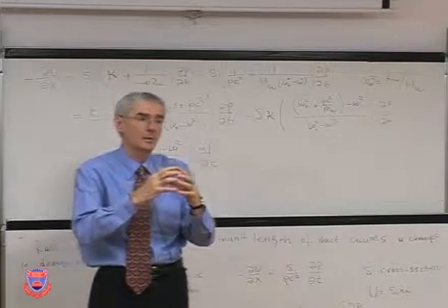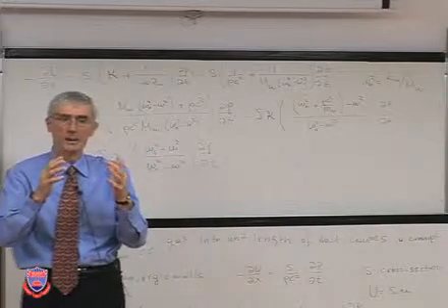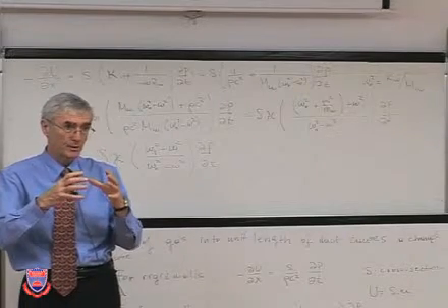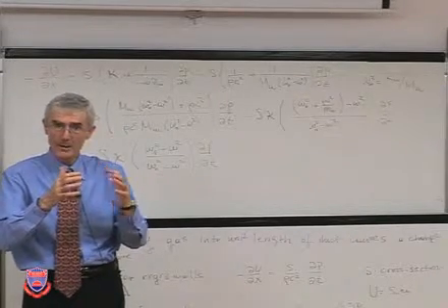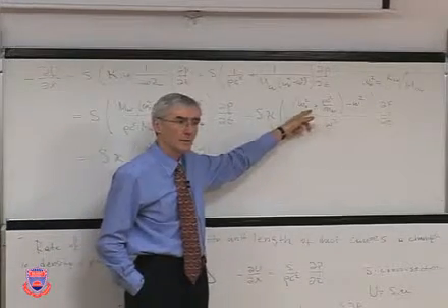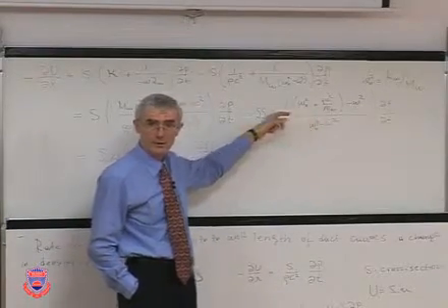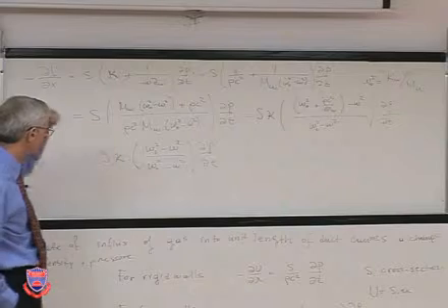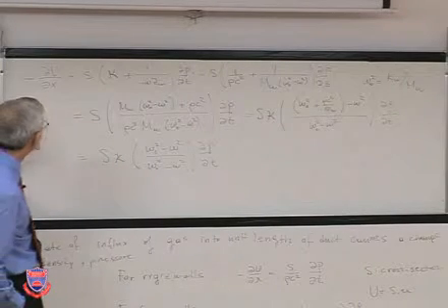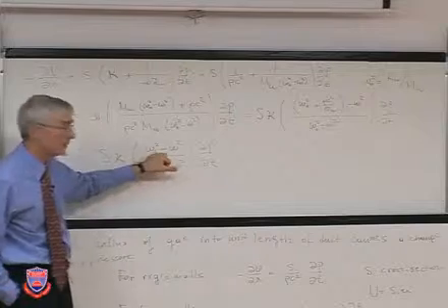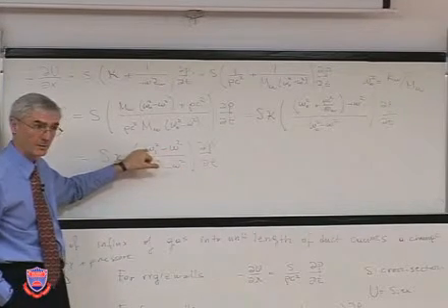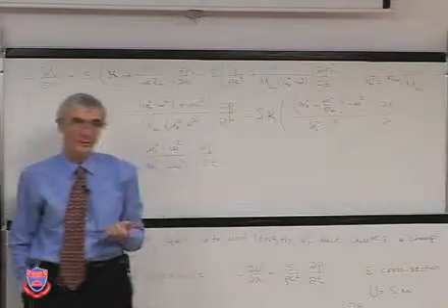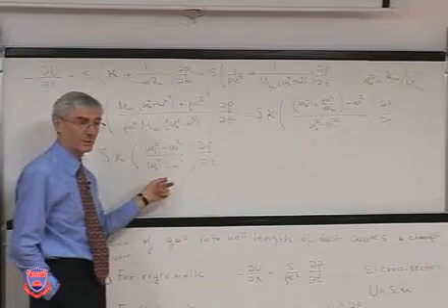Because it's like a balloon, okay? The membrane is not very stiff when you don't have air in it. But the higher the pressure in it is, the stiffness is somewhat different. So this is just a little bit addition to it that changes its stiffness. And it gives it a different frequency. You can see the relationship now. And in fact, the gradient now can be 0 if the frequency of the sound that's coming in is equal to this new frequency, or it could be very large at a very close value.